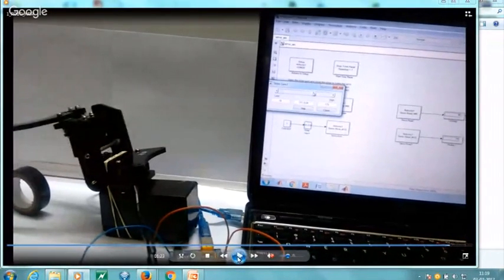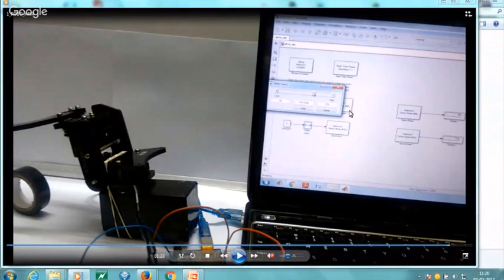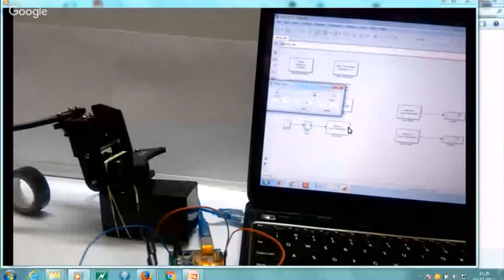And for that purpose, if we want to do some inverter applications, we will generate the PWM pulses or different types of pulses. We will make a diagram in this window and we will send them with the help of some digital input output pins or PWM pins. So we can use optocouplers and MOSFET driver ICs. Whatever you do on your Simulink platform, you can easily connect. Just use these two blocks on this Arduino platform and use your Arduino digital pins for real-time applications. Okay, fine. So this is very useful for your engineering research, and for implementation purposes, you can easily do it.